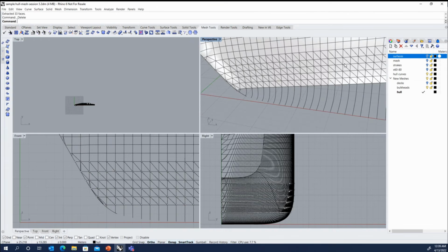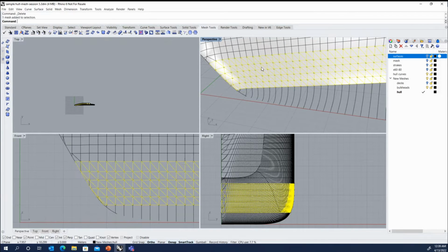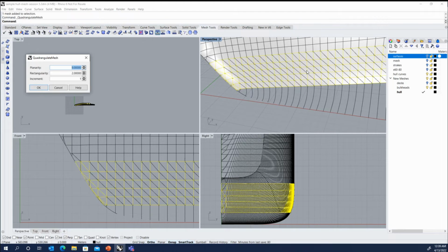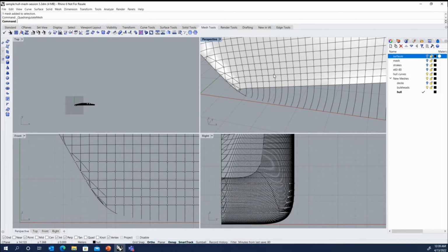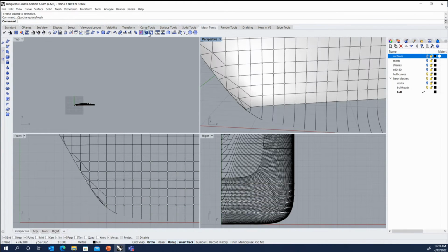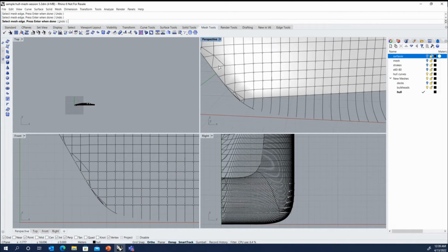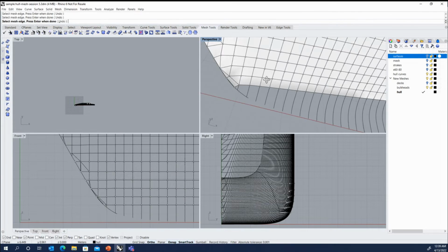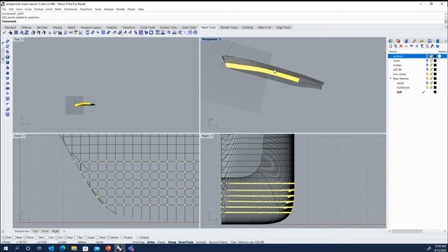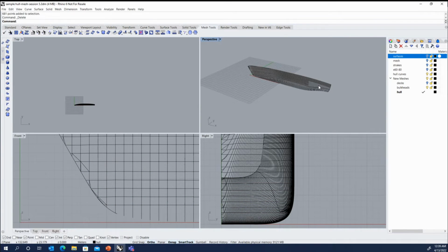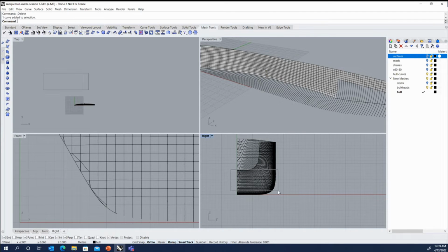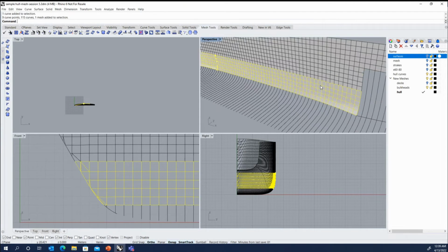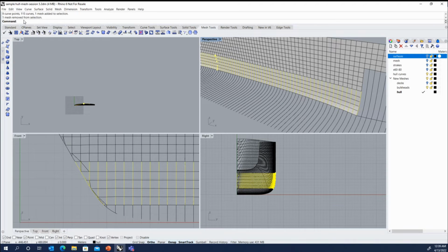Now you can see traces along the horizontally where we want all our stiffener traces, so we can go ahead and quadrangulate the mesh. It's keeping all the ones that we want. We can manually merge a few of these extras. And we'll clean up those points, just select them and delete them. So now we've got a good portion of the hull done here. I will group these curves again and exclude the mesh.